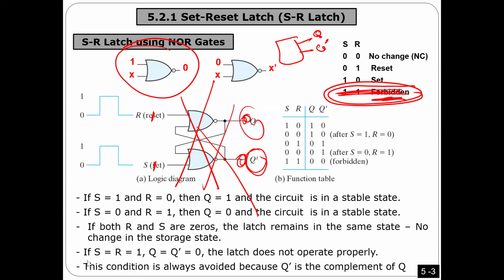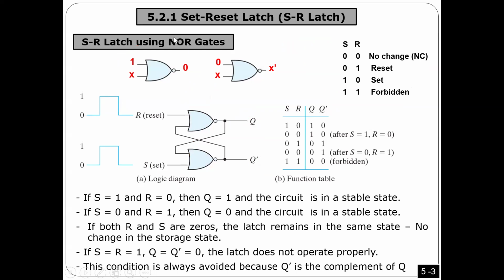So if you want to use the SR flip-flop using NOR, we are going to be limited to only these 3 cases. I'm not going to use this case. You should not use this case. Okay, guys, any questions? I'm going to repeat it.